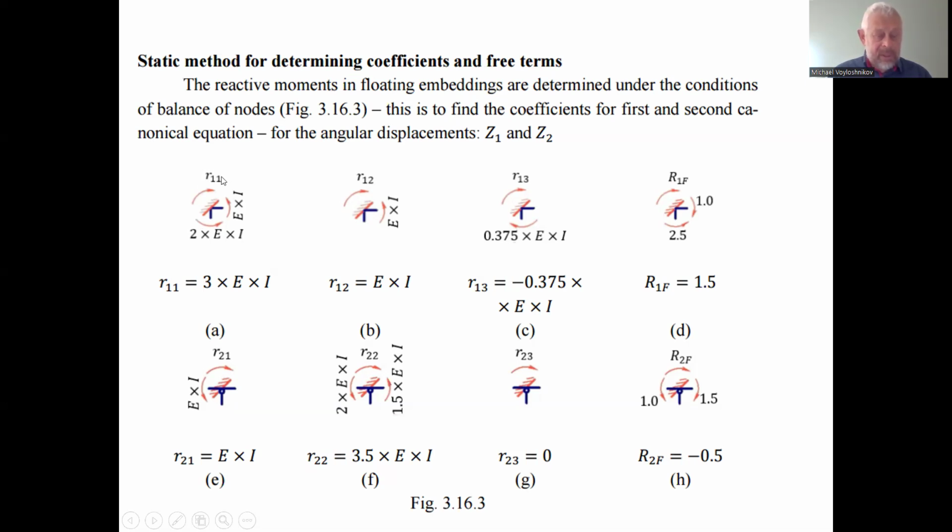Unit effort is the unit kinematic action, not the effort. R11 is the effort in the force direction of the constraint in the first extra support, under the action of the unit kinematic action of the unit angular displacement of this definite support, which is the assumption of the